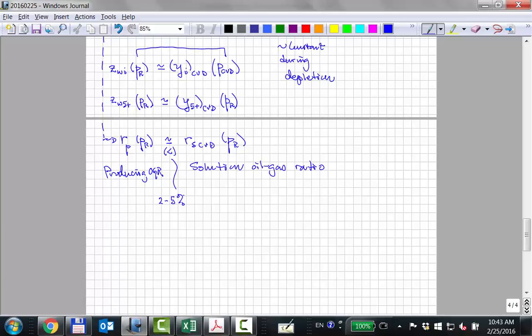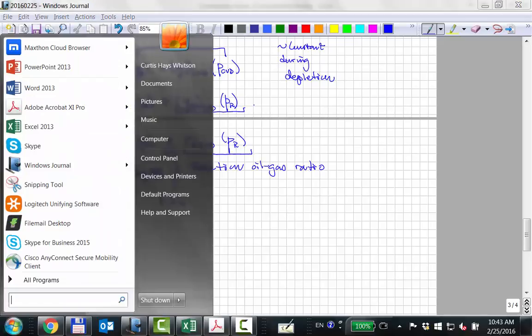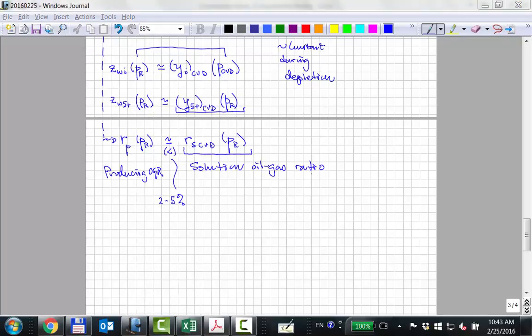It's money. You know, if you calculate barrels, it's going to make a difference. But it's certainly a good rule of thumb approximation. So this laboratory PVT experiment gives us the compositions of the heavies, the C5 plus in our gas. And that gives us a reasonable estimate of our well stream producing composition at the same pressure. We can convert the compositions to barrels per million or whatever unit you want to use.